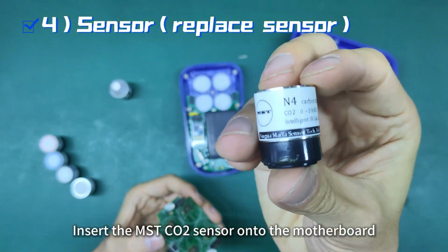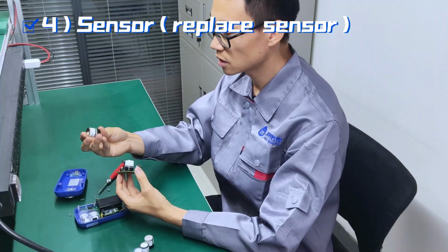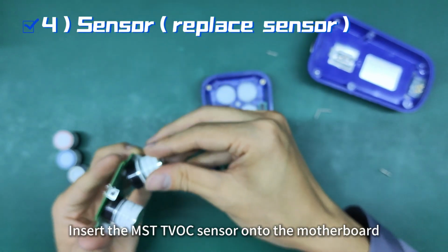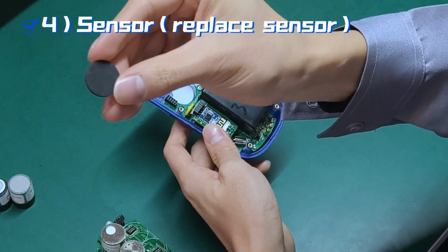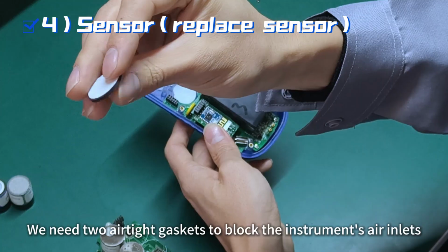Insert the MST CO2 sensor onto the motherboard. Insert the MST PID VOC sensor onto the motherboard. Since only 2 sensors are installed, the other 2 positions are empty. Therefore, we need 2 airtight gaskets to block the instrument's air inlets.